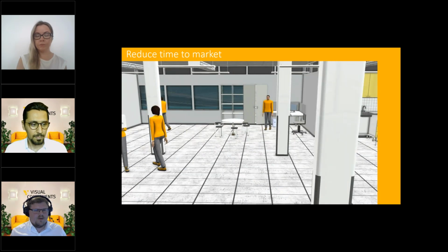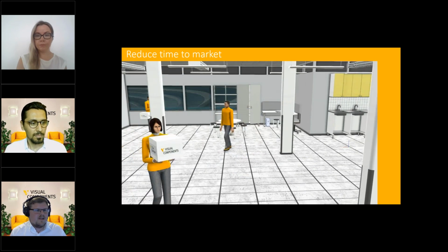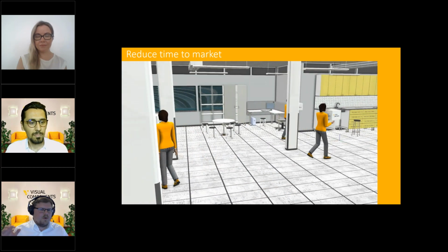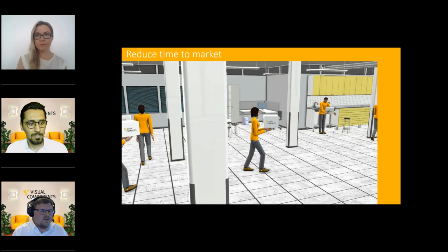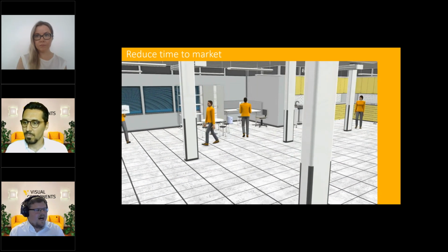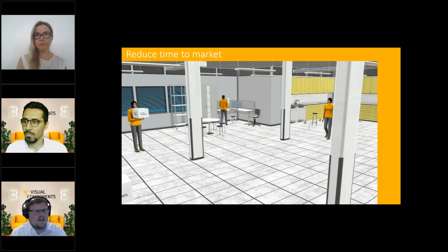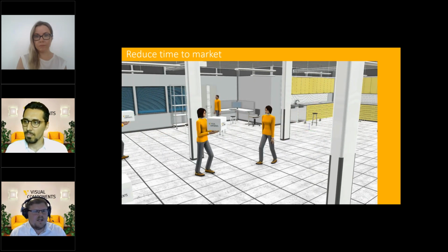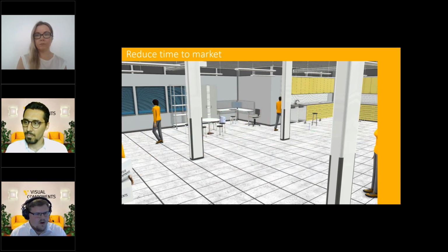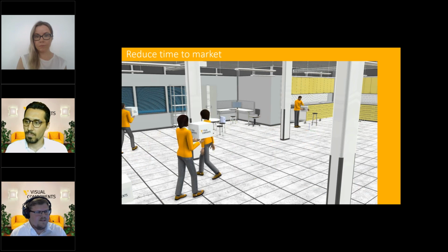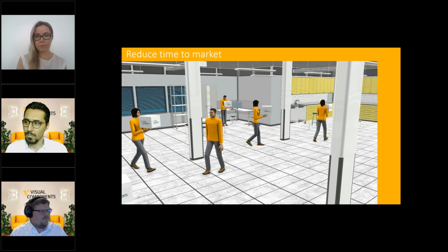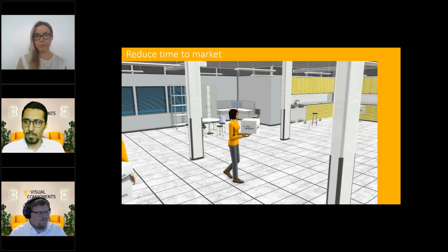So we want to decrease the walking distance, right? So we get the spaghetti diagram of the operators, we check the walking distance. Okay, what happens if we move the material storage closer to this cell? Did it now get further away from something else? How can we subdivide it? And then by going back to the statistics dashboard we were looking at before, we can check the output of the factory. Did it improve or did it get worse? And what happens now with the walking distance and all this kind of wasteful activity that goes on in a factory? So yeah, I would say so.